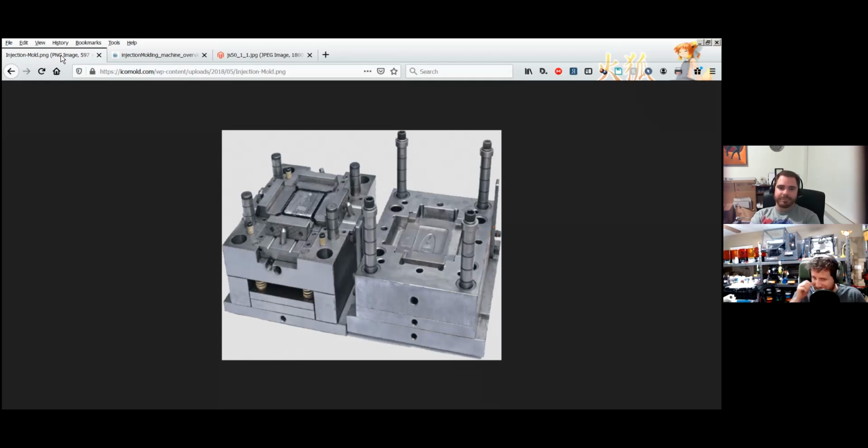Layer times on normal resin are between 7 and 15 seconds, with your bottom layers being somewhere in the minute range. This thing is a 2-minute bottom layer. You need 10 of those. And then your individual layers are between 40 and 60 seconds. So huge amounts of time. I started the rings in the normal resin when the jewelry wax resin was 25% of the way through, and it finished well before the wax prints finished. But if you're looking for extremely high detail stuff, we recommend it.